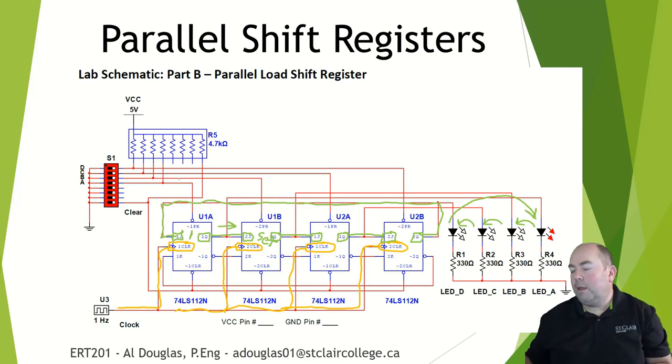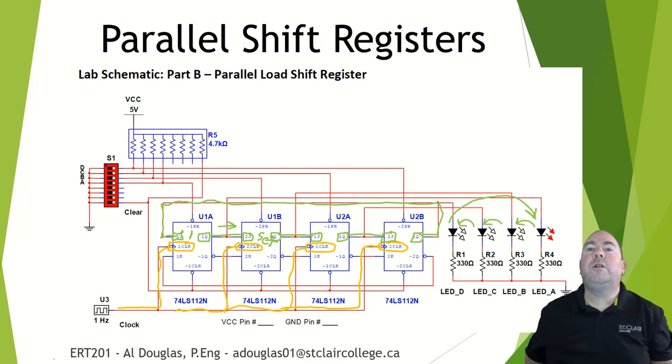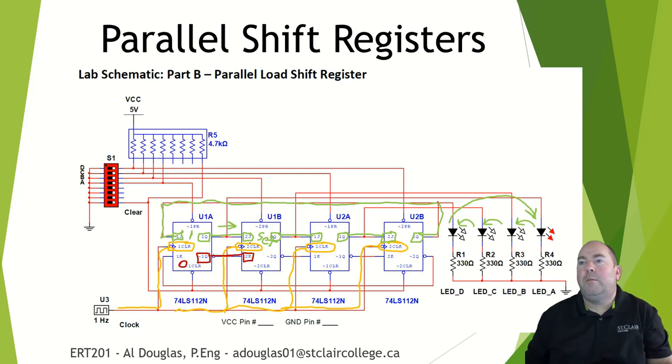Okay? So that was doing the set function by connecting the J and the Q. Let's say we have a 0 in here. A 0 will mean that the Q bar is on. Now what we're going to do here is connect Q bar to the K, because that will trigger a reset and make this 0 transfer over here.